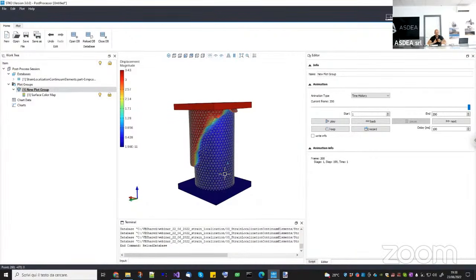So the first topic is that you have to use a real fracture energy, not a specific fracture energy. If it is possible, you have them from experimental results, it's fine. If you have specific fracture energy from experiments, then you need to obtain what was the real fracture energy from which they obtained the specific fracture energy. Typically it is the specific fracture energy times the length of the specimen. Okay, so once you have that, you have the real fracture energy, you can input it in the material model, and you can switch on the automatic regularization. So this is the first part, to ensure that the amount of dissipated energy is independent from the mesh size.